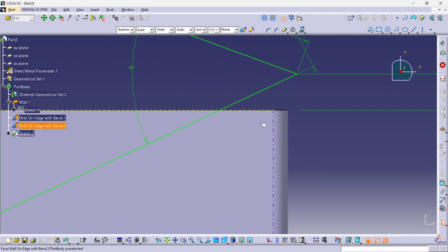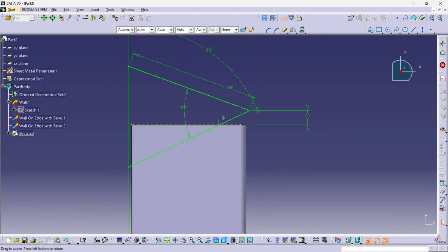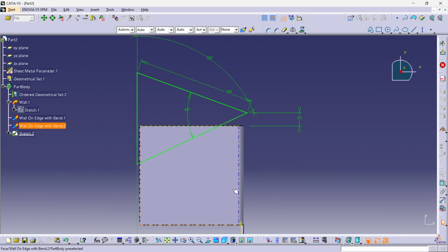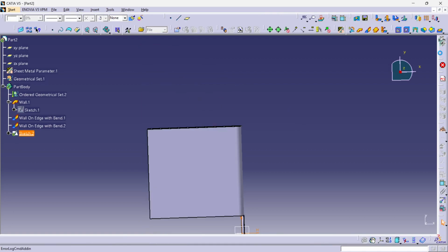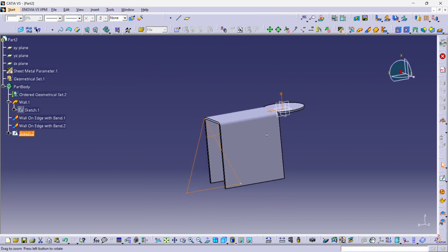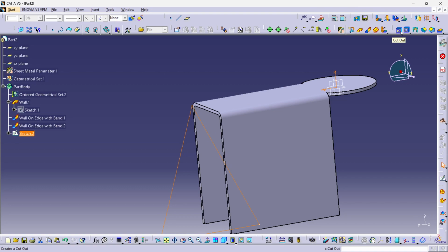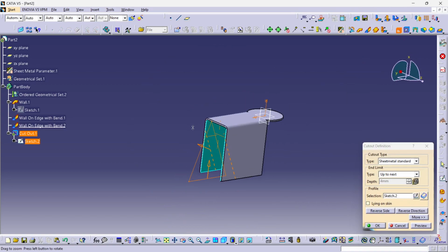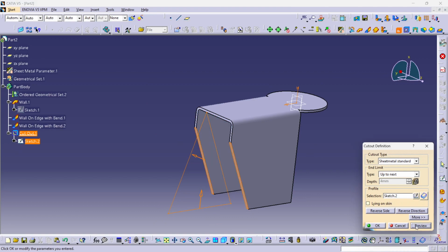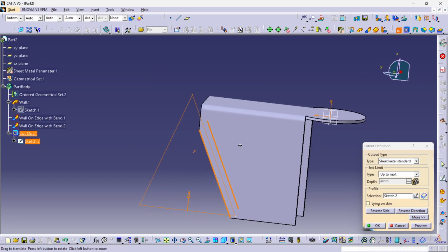Okay, make sure the line is dotted, like this dash line, so it is a construction line and doesn't cause any difficulties when going for further things. Okay, so all is good. Take a look and just come back. Now use the command called cutout, right? So it will cut out the things. Preview. Yep, like this. Looks good.